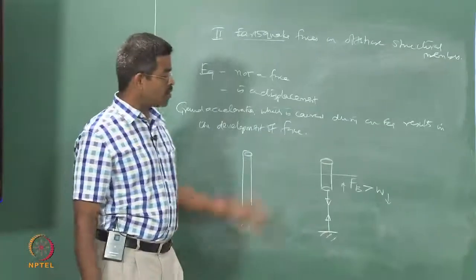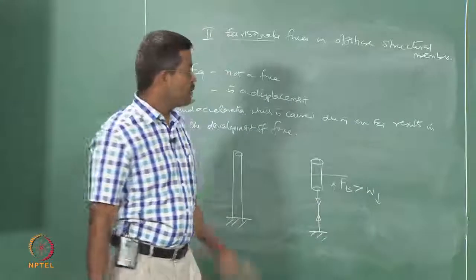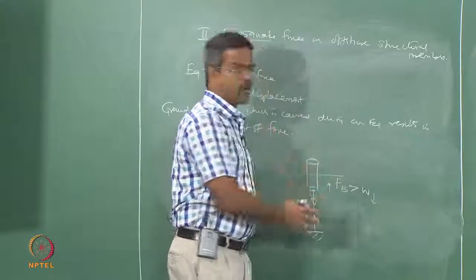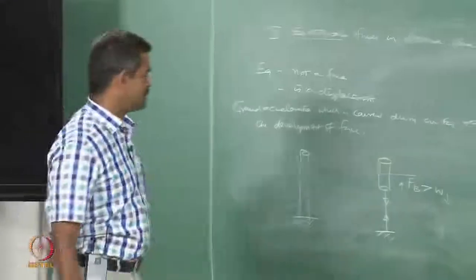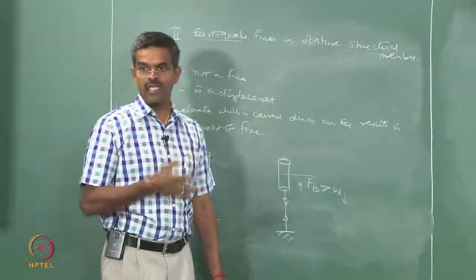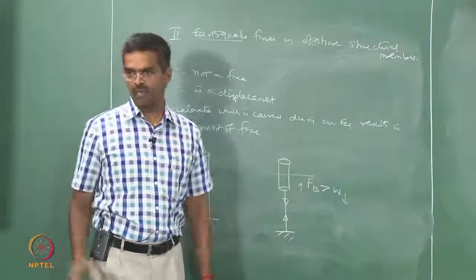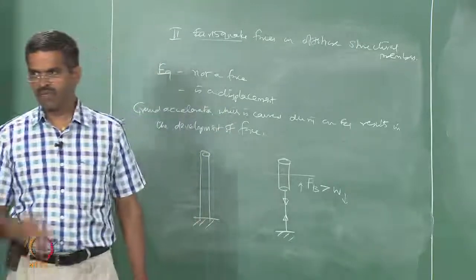Then one can ask me a counter question: why has the design evolved for installation purposes? That is the beauty in offshore structures, because in offshore structural schemes, installation, commissioning, decommissioning is about 70% or 80% of the cost of the structure itself. It is very expensive. Therefore, we should have a mechanism. There are very special equipments, cranes available. There is a weather window within which you have got to operate, etc. All consequences are there. We already vaguely know this, at least what are the forces coming on.